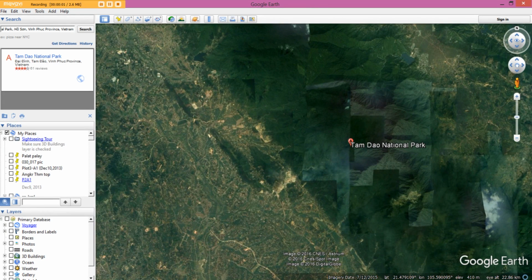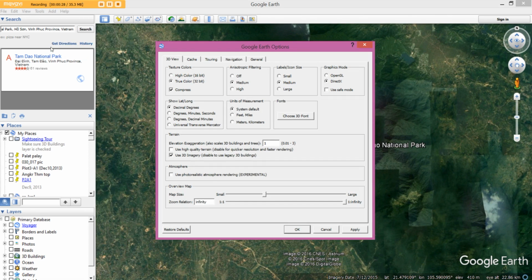In this lecture, I will demonstrate how we can convert our spatial data between two different coordinate reference systems. As you recall, the two coordinate systems that we are working with are the geographic coordinates, things like latitudes and longitudes in degrees, and the projected coordinate system, things like UTM, which are expressed in terms of meters.